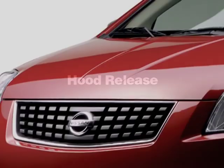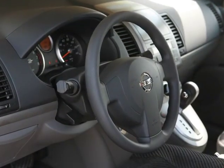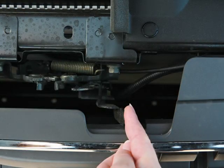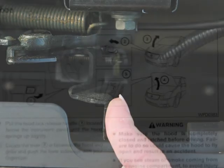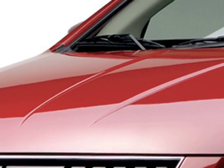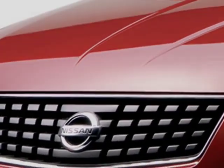Hood release. To open the hood, pull this hood release handle located below the driver's side instrument panel. The hood will spring up slightly. Outside the vehicle, push this lever at the front of the hood to the side as shown. Insert the support rod into the slot on the underside of the hood. When closing the hood, lower it slowly and look to see that it is latched firmly.